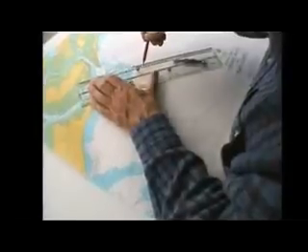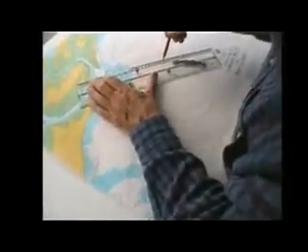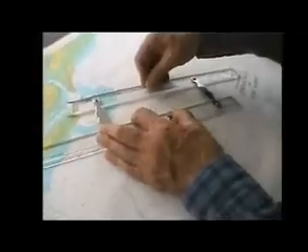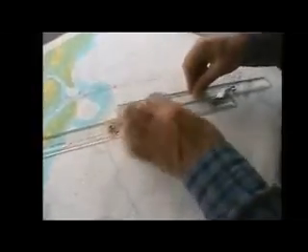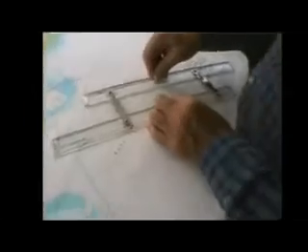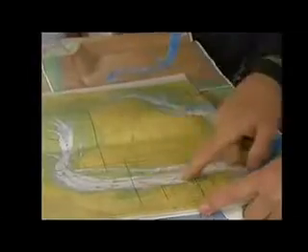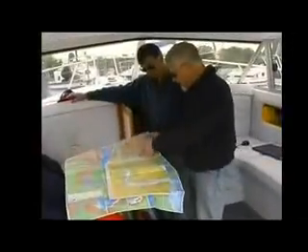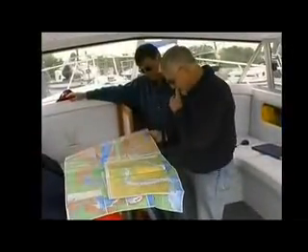You will then know how to use the appropriate navigation instruments, such as the compass, parallel ruler and dividers, to get the most out of the information on your chart. You'll get more pleasure out of planning your voyages, and you'll feel more secure if something does go wrong with your GPS. In summary, by studying the chart carefully before you set off, you should be able to navigate safely, as long as you take the tides and weather forecasts into consideration. If you share this information with your crew members, they will find it interesting, reassuring, and they should be able to help you navigate along the way.